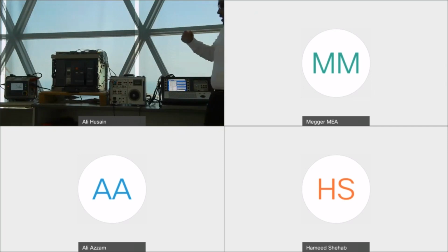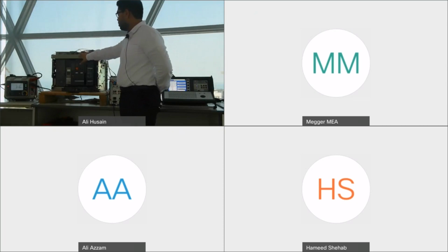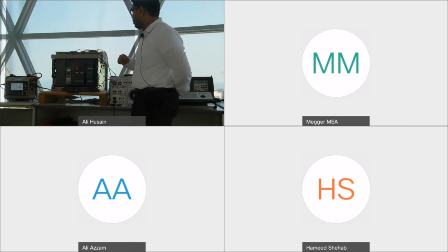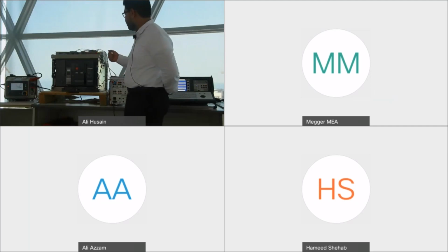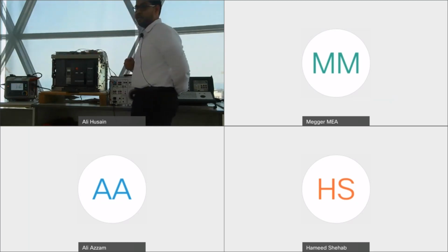And then I have here my circuit breaker, my connection to the control circuitry, the close and open pulses, and also the positive and negative. And also to make our life easier, I have connected the motor of the breaker to automatically charge the mechanism whenever I want to do testing for open or close operation.